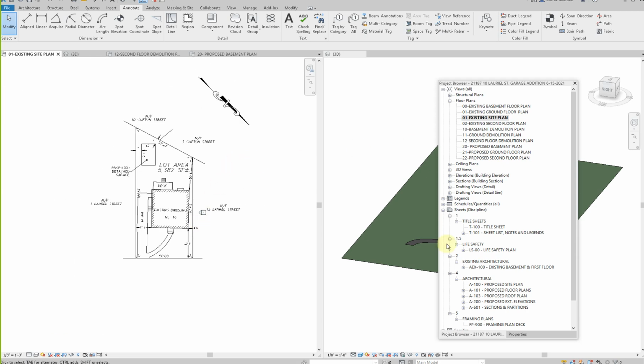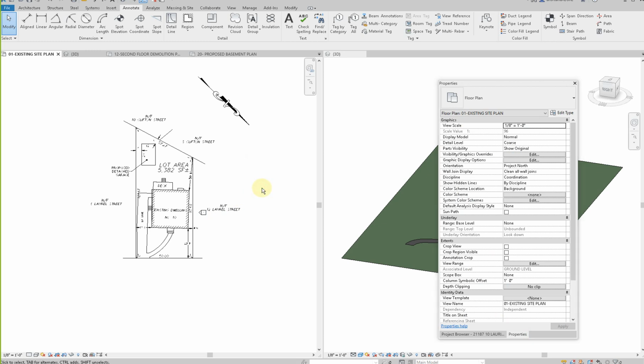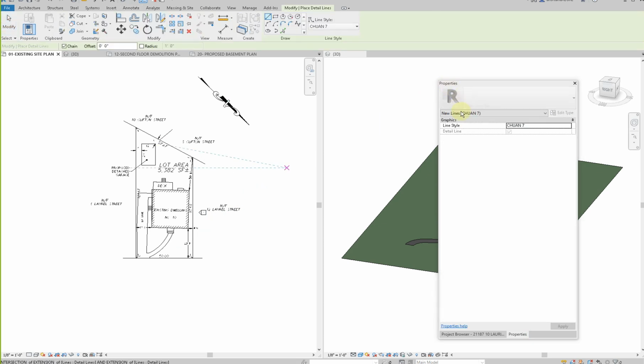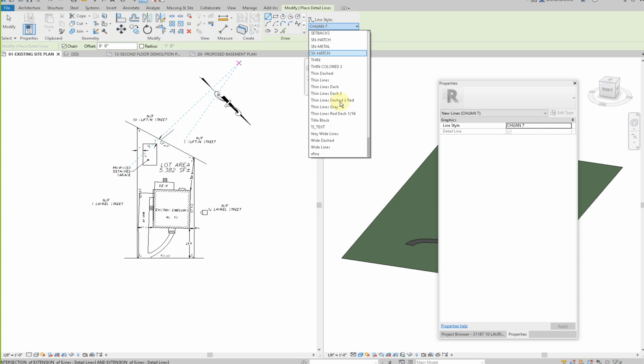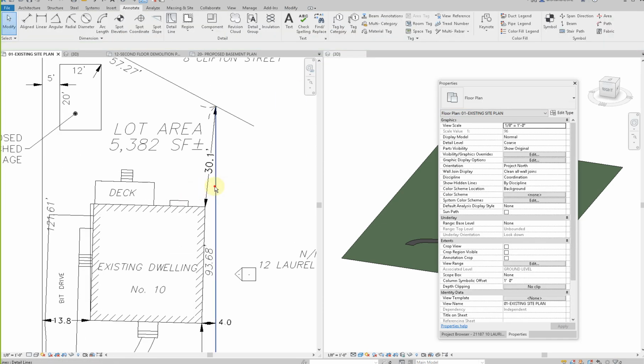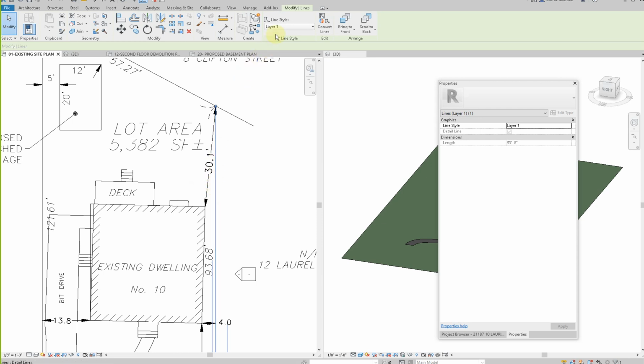Well, the bad things about it is that then if you say detail line, you're gonna start seeing a bunch of lines that show up in our model that we didn't necessarily make or add, because all of these lines that are here are not part of our lines. Like it's layers from Revit, from CAD, and it starts getting super messy.